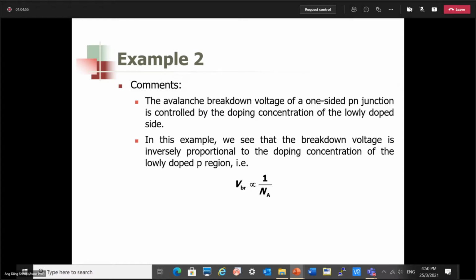On the other hand, avalanche breakdown is destructive because the current that flows during avalanche breakdown can increase very significantly and uncontrollably due to the onset of impact ionization and a chain reaction process that causes more and more carriers to be generated through impact ionization. Zener breakdown therefore has a lot of practical value. As mentioned, in circuits, some diodes are designed to operate as Zener breakdown diodes, whereas avalanche breakdown is never considered to be useful due to its destructive process.